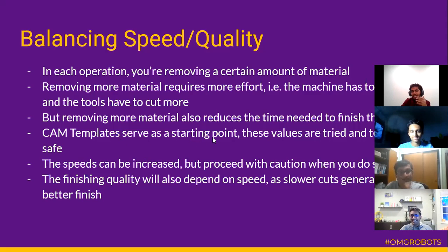So that's why, like I said, if we have templates for the CAM, those are our starting points. These are values you've tried and tested on the CNC and they're very safe. Once you start going beyond them, it's okay to do so. Just be cautious, because once you overstep the line, you're going to break something, and you'll also get lower quality. Lower quality is bad because, for a bearing hole for example, your bearings won't fit or they're off center. That's a problem in terms of performance and also looks sometimes. If the bearing hole has a really rough finish, it doesn't look that great, and that's generally not good for assembling things either.